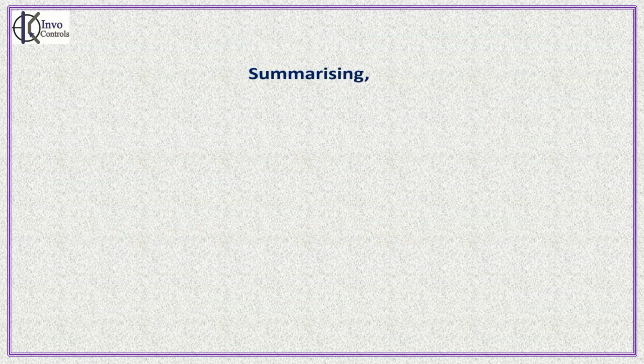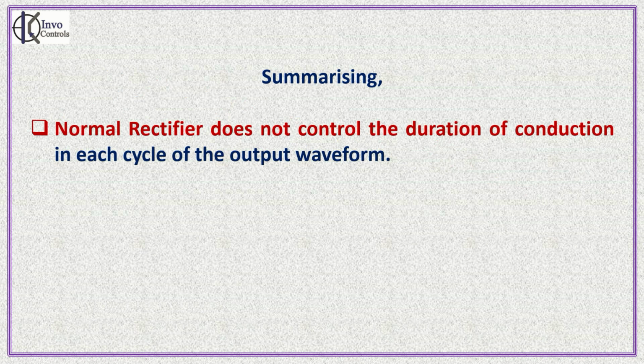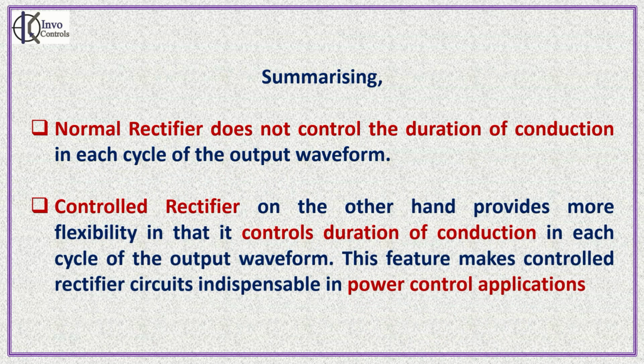Summarizing, we may say that number one, the normal rectifier does not control the duration of conduction in each cycle of the output waveform, whereas controlled rectifier provides more flexibility in that it controls duration of conduction in each cycle of the output waveform.